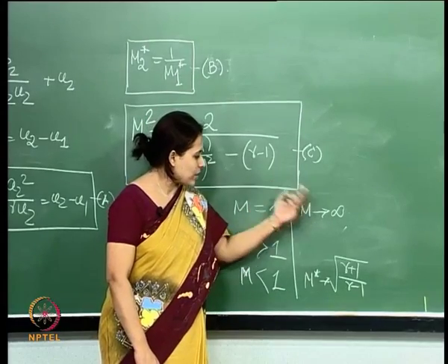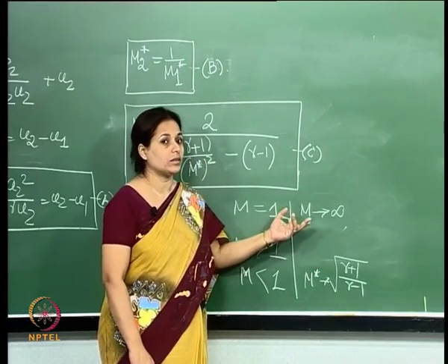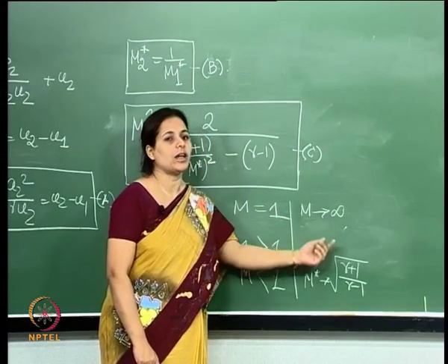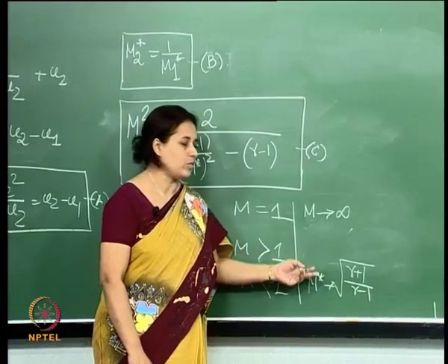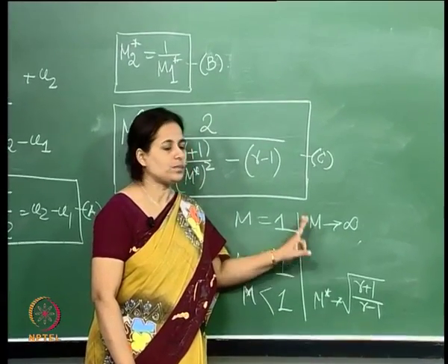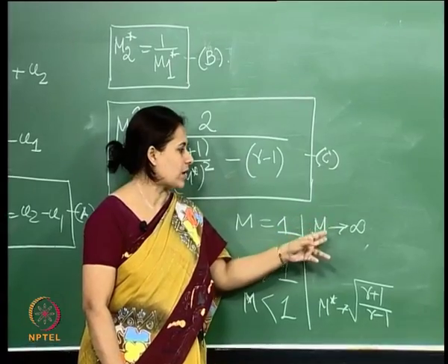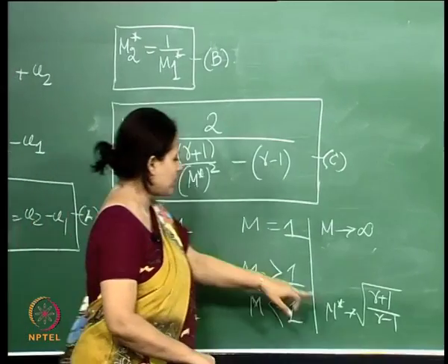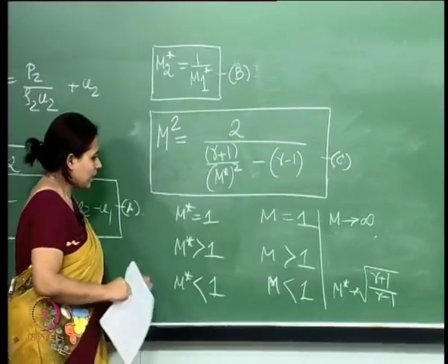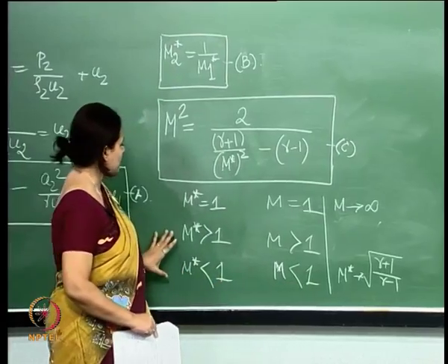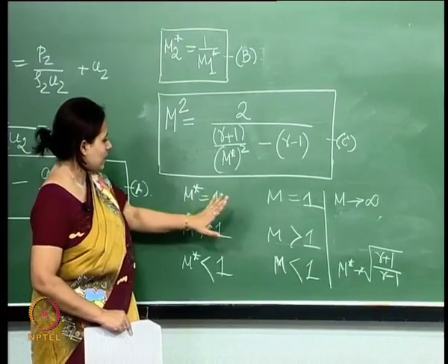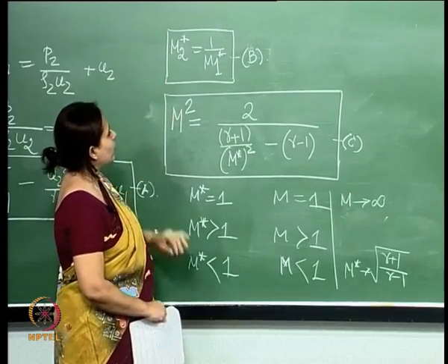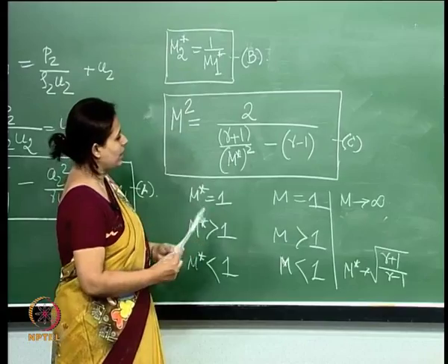Okay. So, whether in those conditions we will also have a shock wave is something that we still need to see. There is only a finite value of the characteristic Mach number that we will reach even if I increase my incoming Mach number to infinity, even if I make it infinitely large. That is what I understand from here. Now, let us use this information, the relation between m star and m, and try to get an inference for m1 and m2.